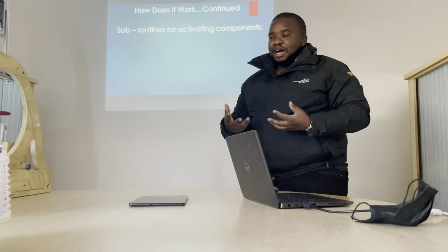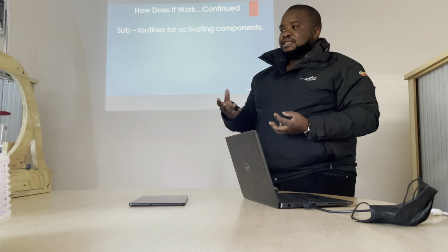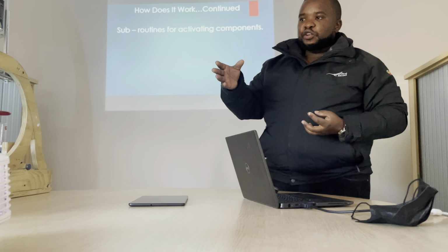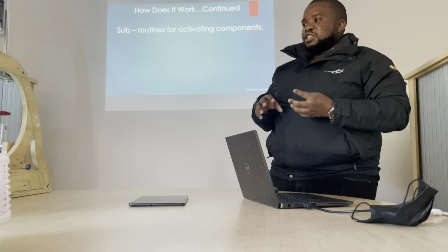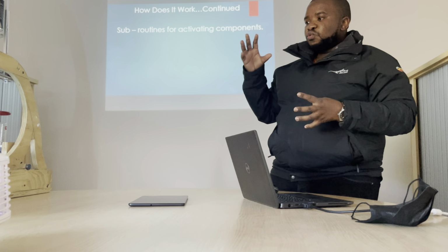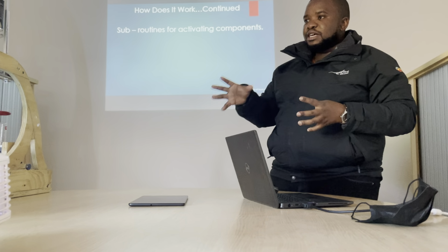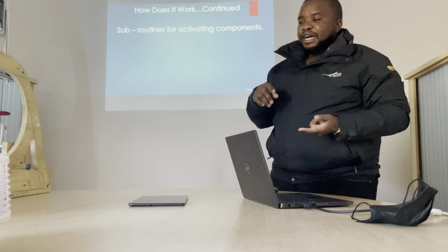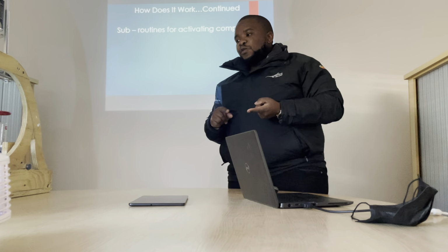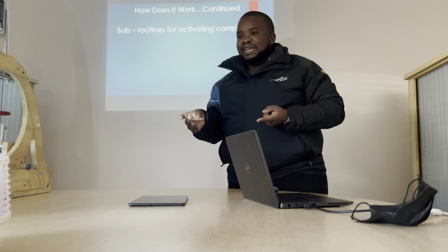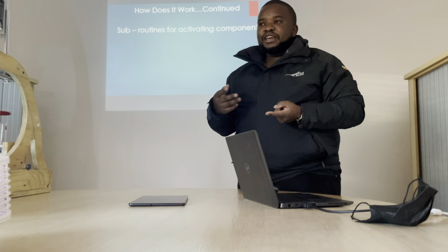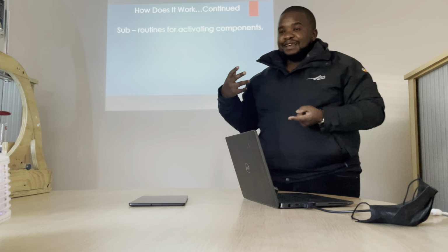Further on how it works, there are programmed subroutines in the microcontroller. I've basically modularized all the subroutines to take care of the individual aspects of the machine. So you will find a single subroutine for the motion of the slider. The slider moves back and forth, and that's one subroutine.